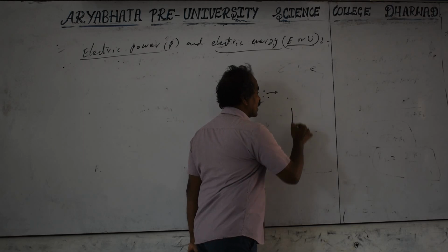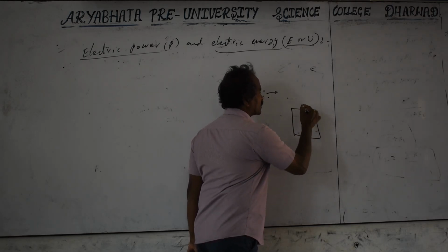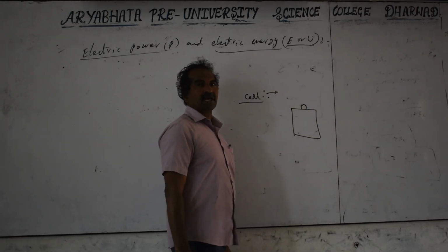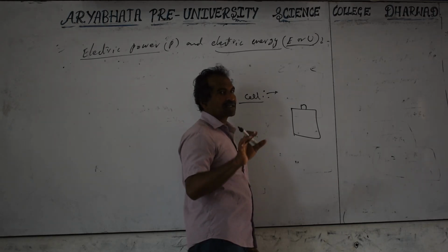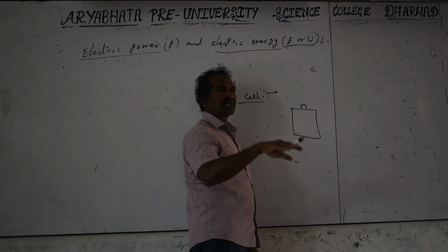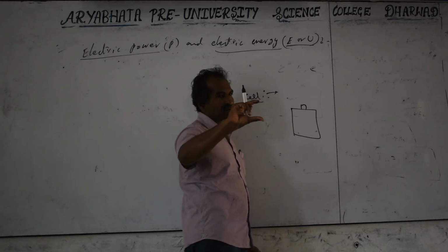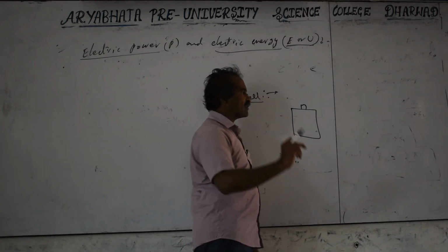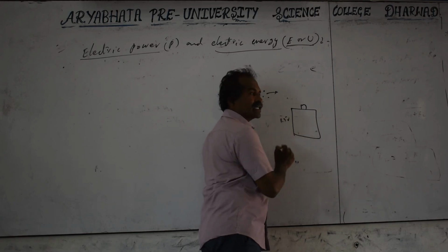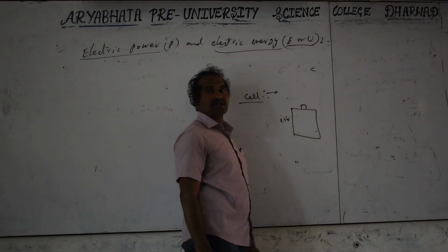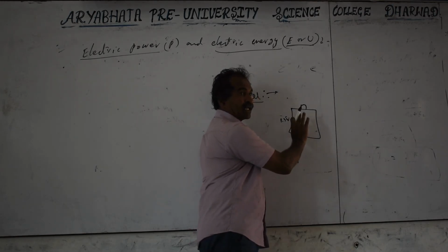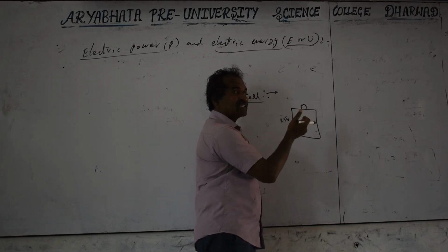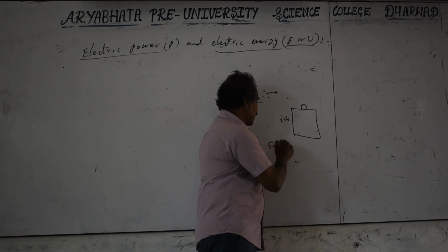This cell contains electrolyte. So it is based on some liquid state or a paste-like material, but wetness is compulsory, not dry ones. The name dry cell is also used, but they are not really dry cells. In the houses, for the battery cells, you will find a value written on it as 1.5 volts. That is not an electric voltage. It is actually called the electromotive force, the total voltage a cell can provide. The maximum voltage it can provide is called the EMF.